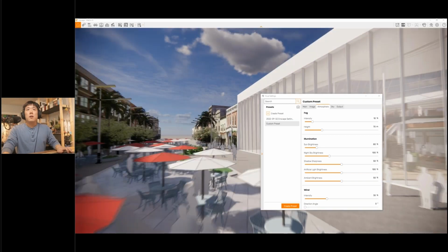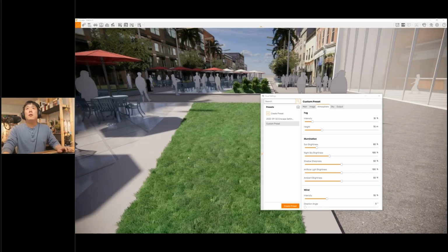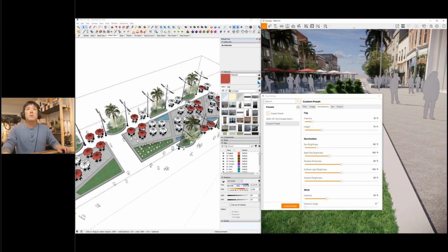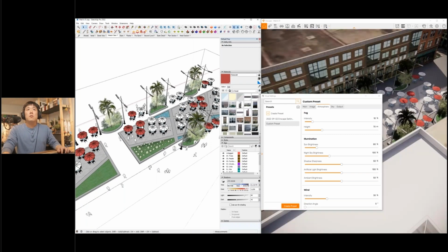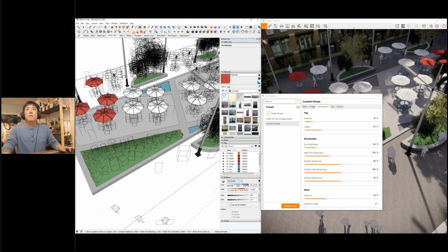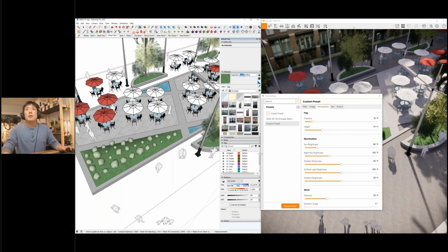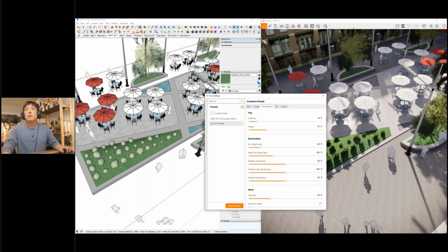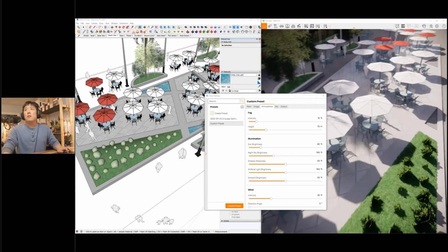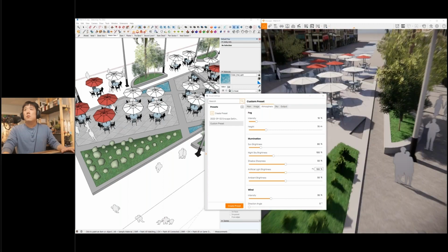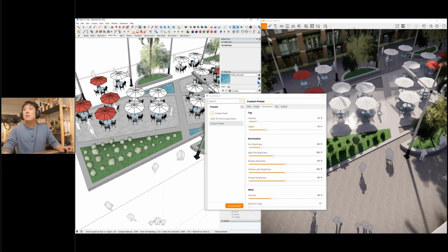By the way, once you designate a keyword inside of SketchUp, for example when you have a material with grass in the middle of its name, it will appear as actual grass inside of your Enscape screen. Same thing for water. If you have water and it has the name water, then it will appear as water. I'm not sure why that one isn't.